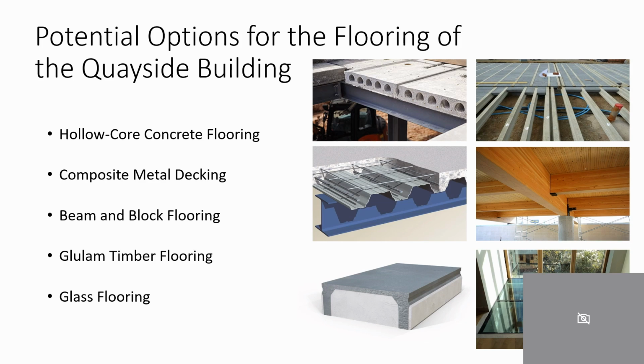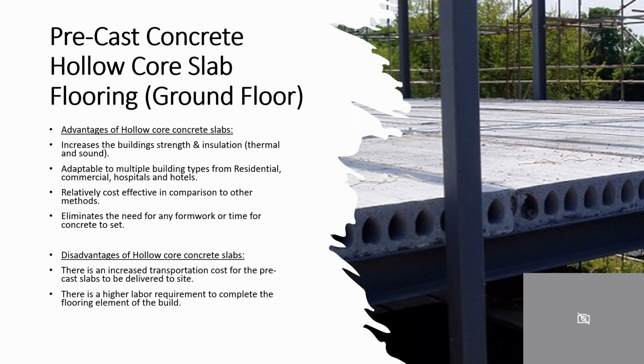So for the first one, precast concrete flooring is a highly versatile method of construction used to provide stability and strength under its own weight, with the ability to withstand the weight of imposed loads that may be placed above. The concrete slabs are cured off-site to minimise handling and construction on site, and the support system is usually in the shape of beams, columns and walls, which will support the structure against the different loads, for example the wind loads, snow loads and live loads within the building.